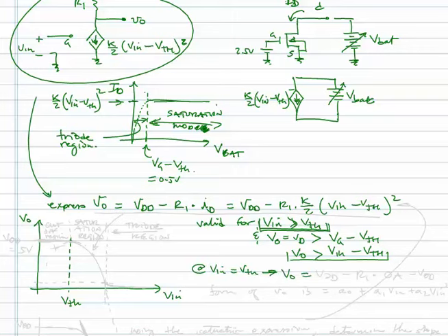So right here I've got VDD, which in my case I drew as 5 volts. You're going to do it for 10 volts. Now from then on, the form of Vo is some constant A0 plus, if you expand the Vin minus V threshold, some constant A1 times Vin, and then some constant A2 times Vin squared.